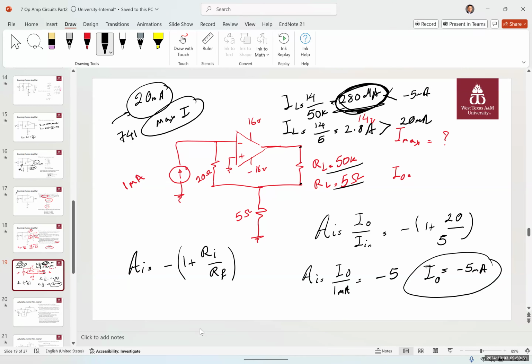Does it make sense? It's exactly like an outlet. The fuse is rated to 10 amps, so you can get 10 amps out of this outlet. But if you connect a charger to it, because you have a high resistance load, the maximum current that you're taking from this outlet is 5 milliamps, for example, or 10 milliamps.